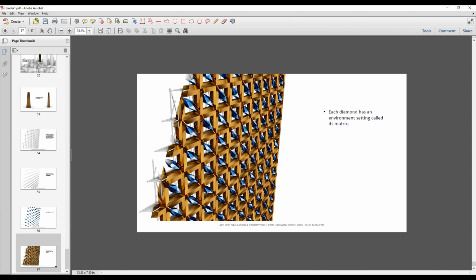A square is not a rectangle, but a rectangle can be a square. And a spline could approximate a circle, but wouldn't be a circle. So I never model things with circles, I only model them with splines, because a spline can approximate a circle, but can also be a blobby, nondescript type of geometry. So there are ways you can cheat, because you don't know ultimately where this thing is going to end up. You try to build flexibility into the code at the front end so that you don't have to rebuild it later.